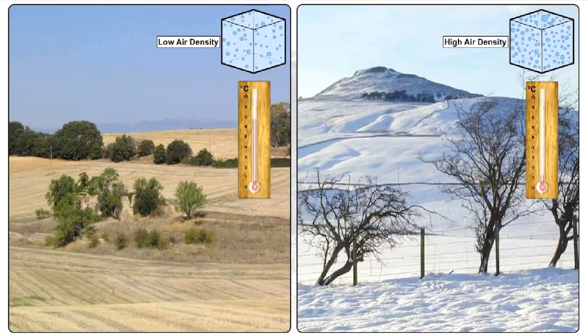The local air temperature will also have a direct effect on it. If the temperature of an airfield is higher than the ISA temperature for the airfield elevation, then the air density will be lower in value than the standard, and thus the density altitude will be higher than the airfield elevation.